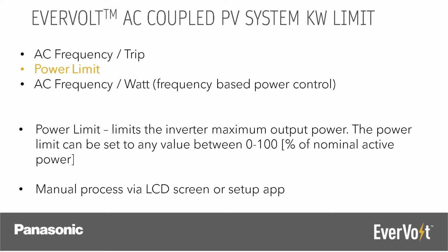If the power is still too much from the PV inverter and there's nowhere for that power to go into the loads or into the batteries, then what can be done is a manual setting on many PV inverters will allow you to limit that power output. For example, if you have a 6 kilowatt PV inverter, you could manually set a limit for during a grid outage, so that inverter will only be able to output 4 kilowatts if you want to match your battery load or your house loads.